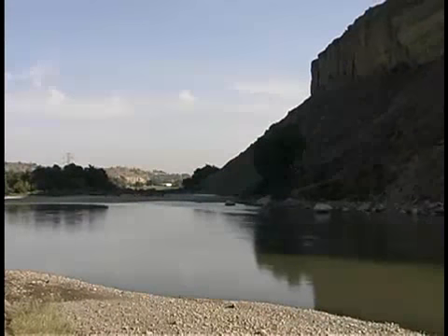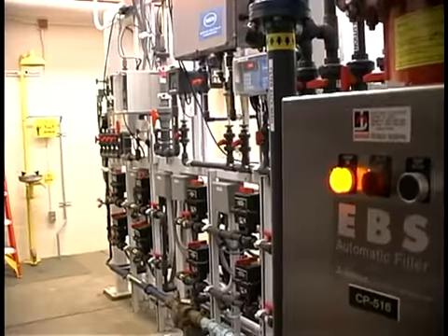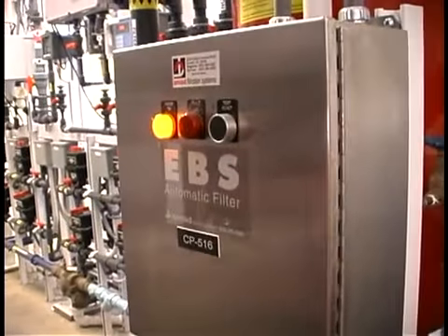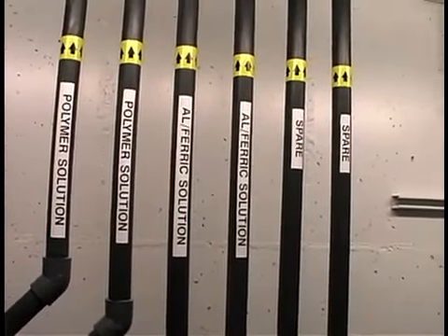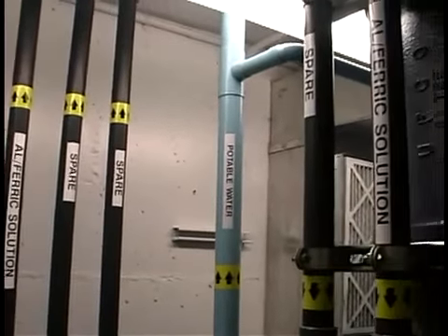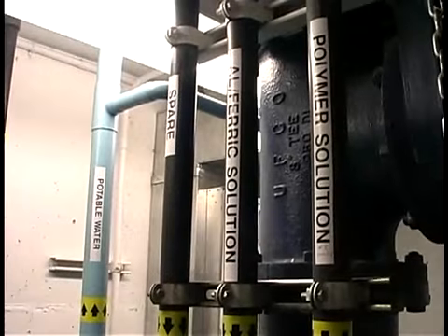Our treatment system here is a full conventional plant. We coagulate, flocculate, sedimentation, and then through filtration. We use a polyaluminum hydroxychloride, PACL, which is an alum blend, a proprietary alum blend. Prior to that, we used ferric chloride. Prior to that, we used alum. We went to ferric chloride because of our arsenic problems and when arsenic became an issue in the early 90s.